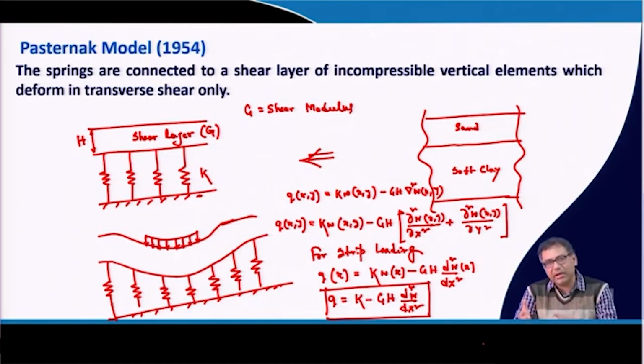But that can be done, and researchers have already incorporated the time dependent effect into this model by replacing the spring with a spring and dashpot. The spring will give you the settlement and the dashpot will give you the time dependent behavior.